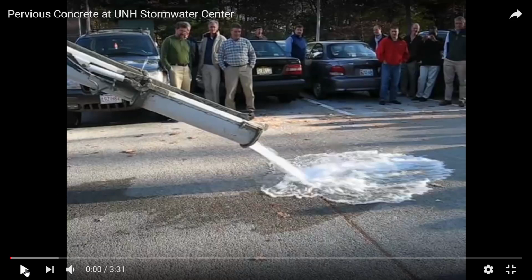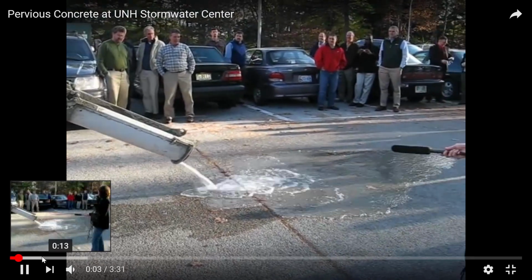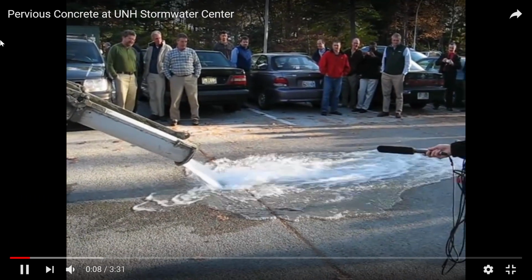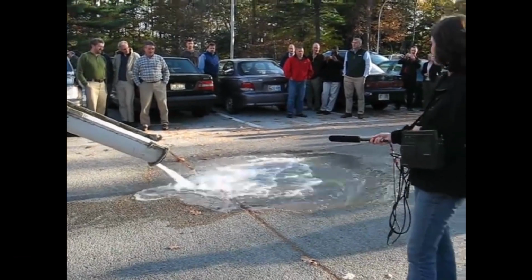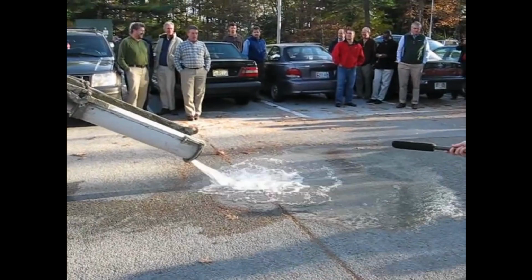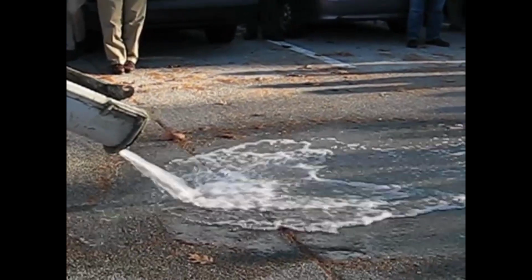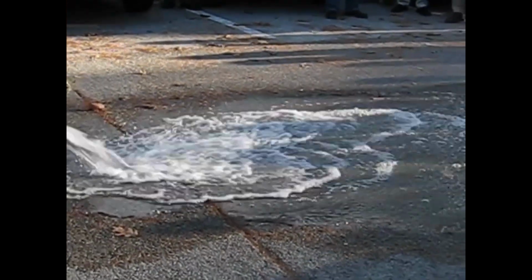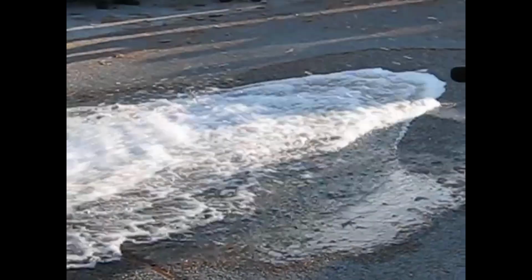And here is some porous concrete at the University of New Hampshire, where they're dumping water in there, and you can notice it just keeps absorbing it. Ordinary concrete, the water would be running off. But in this case, what they've done is they've removed the sand from the concrete mix. And so it's cement and it's pea gravel, but there are voids there that are interconnected where the water can actually travel through the concrete and down into the gravel subsurface that they've got underneath it.